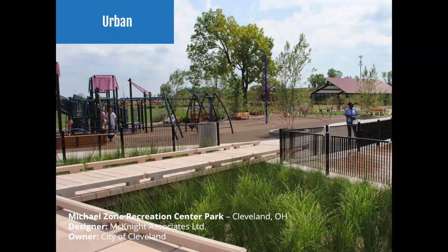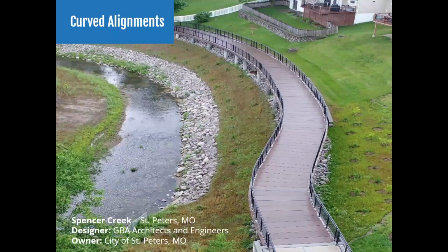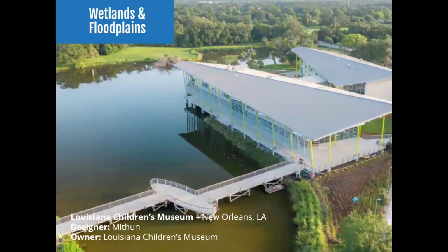And then you can also use boardwalk systems as a feature. Here you see them using it to cross a rain garden at an urban park. And then the next slide shows how you can use different systems to generate curved segments. For precast, we like to do things nice and rectangular, but that doesn't always fit the site. So we'll use a series of rectangular with trapezoidal pieces to make up a chorded segment to follow the natural curvature.